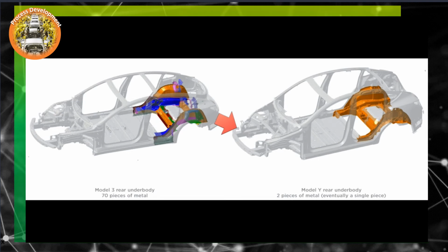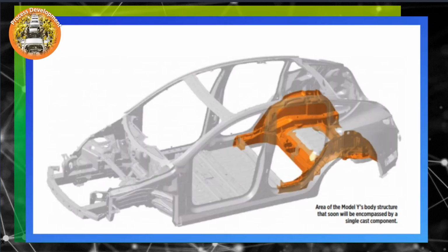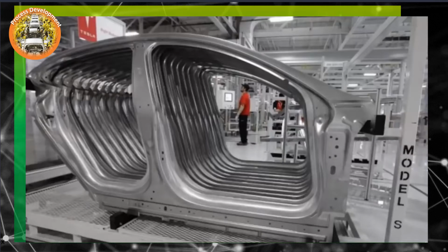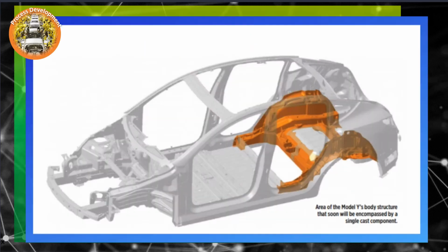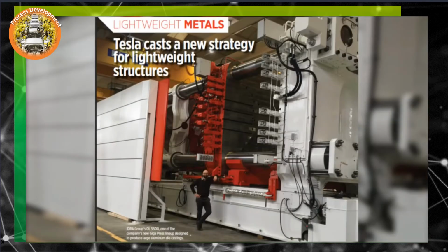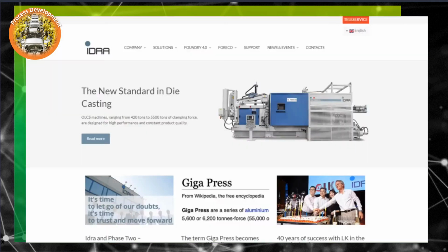88 pounds of molten alloy gets injected and 2 minutes later the result emerges. This final two-part unit eliminates 80 parts and about 700 joints in the previous assemblies on the other car models. Tesla's house-size gigapress for the Model Y production of the rear underbody aluminum casting will decrease the labor cost by about 20 to 30% because the pieces would traditionally be assembled using multiple stampings and assembly operations.